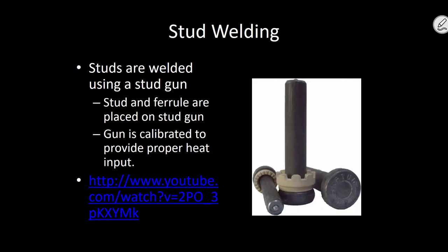Now, if you look here, see how on the end of the stud there's kind of this little nub sticking out? Okay, so here's what happens when you install a shear stud. You have this large stud gun that you load a stud into, and it basically conducts an electric current. You place that over the girder and you hit the trigger.